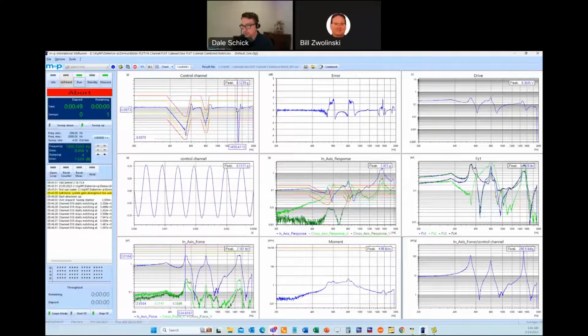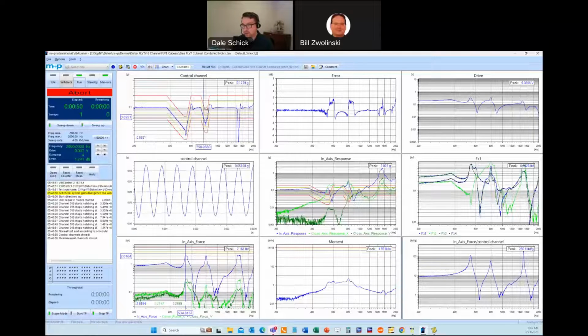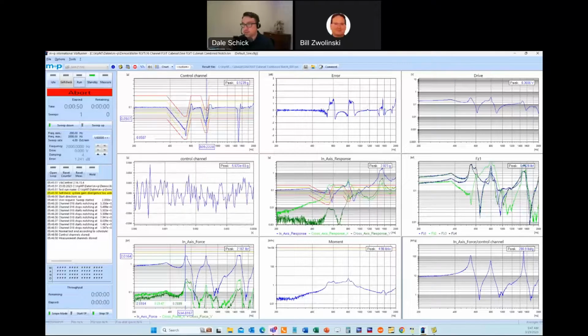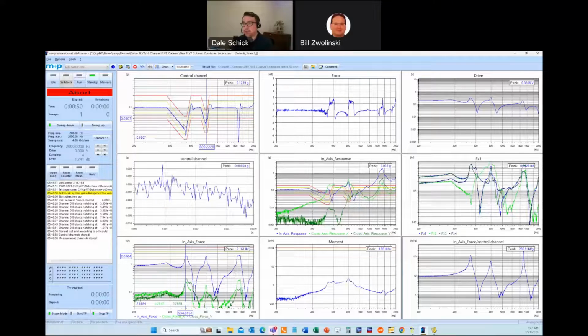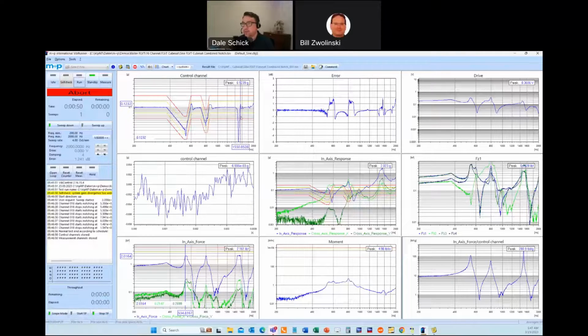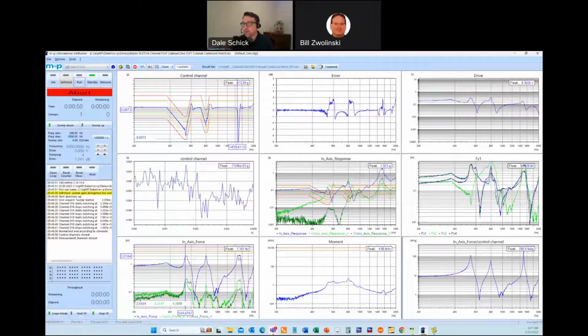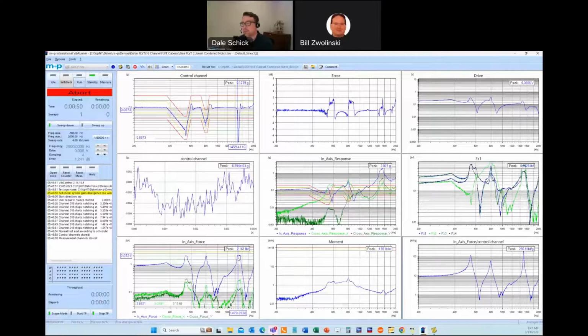Now, one advantage to doing this combined notch is that although my manual analysis of the 2 bathtubs that I defined was effective at reducing the input, this one that I did not predict over here was effectively captured by the in-axis force response and its notching.